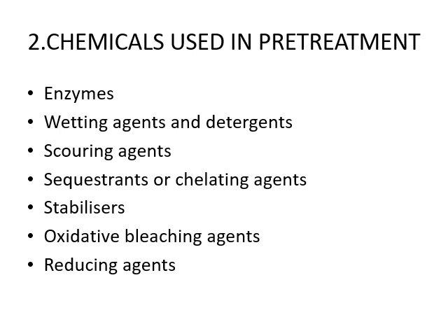While selecting these chemicals, one should see that the optimum concentration and proper combination of chemicals are used, because excess concentration of chemicals will demand more consumption of water, and traces of chemicals will remain over the fiber, which will create a problem during dyeing.